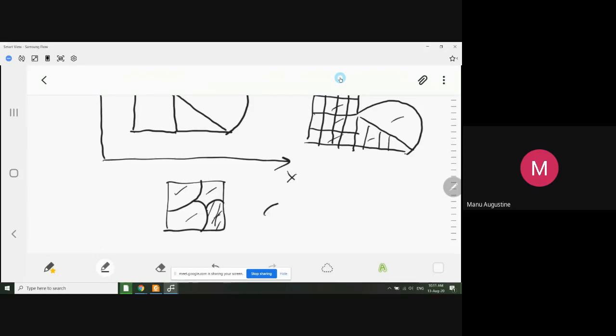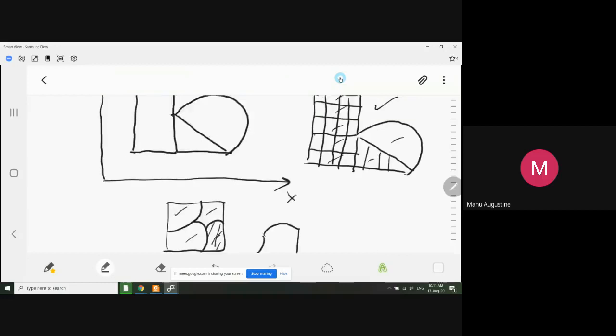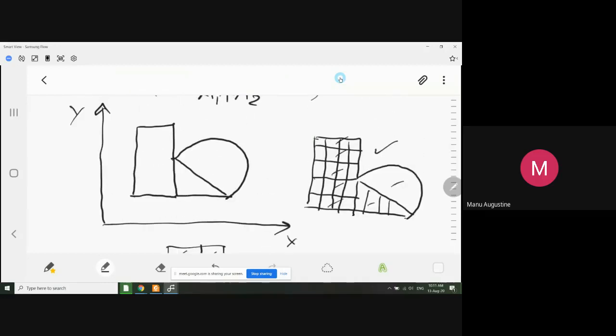Have you seen a geometry like this ever in your life? So you should never divide the composite section into absurd geometries. You should try to divide the given geometry into recognizable standard geometries. By recognizable standard geometries, I mean the geometries of which the centroid is already known to you.